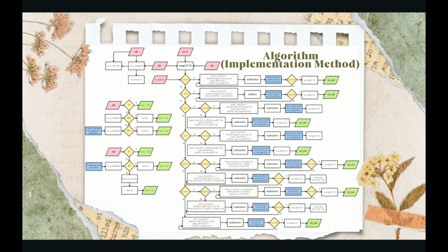As for our computation of each mode, if the function select is max, then we will use the adder to do comparison and store the result in the ACC register, which will be reused until the round is completed. After the computation is completed, we will send the data to the IoT output. Min is similar to max, but we choose the one with the smaller value to be stored. In the function of average, we will add every value together and right shift 3 times before data output.